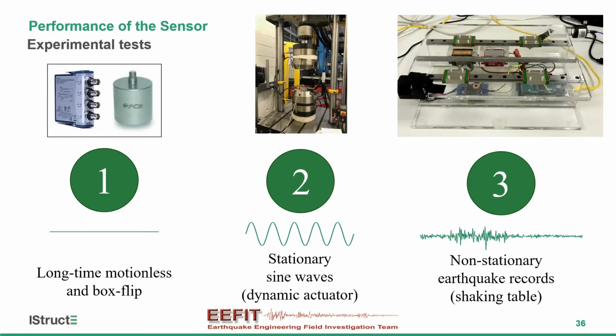And before I show you the results, that's going to be the main part of the presentation. For benchmarking the sensors, we use a PCB high fidelity commercial sensor that is an accelerometer basically, and a typical data acquisition system from National Instruments. So this is going to be our benchmark. The benchmark is not the input of the actuator or the input of the shaking table, it is measuring exactly the same at the same time with a high fidelity sensor. So I'm going to refer to this as a reference or transducer.